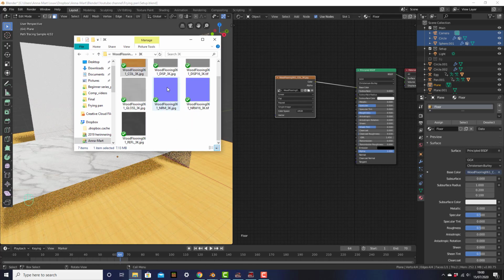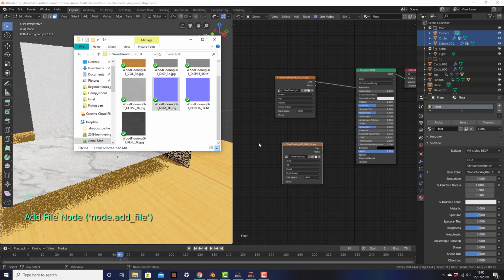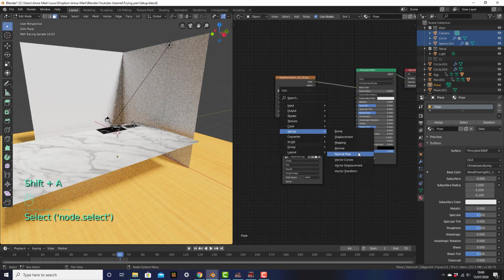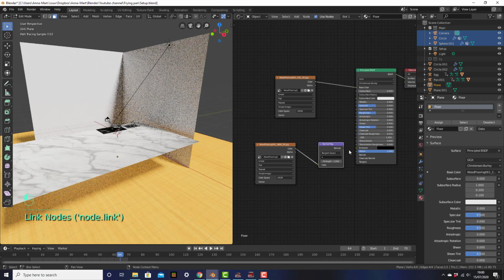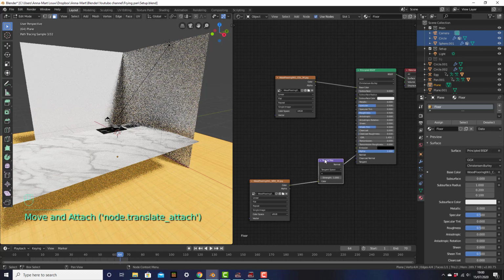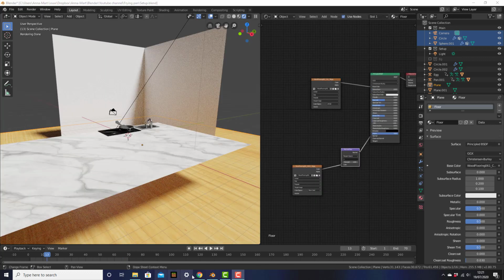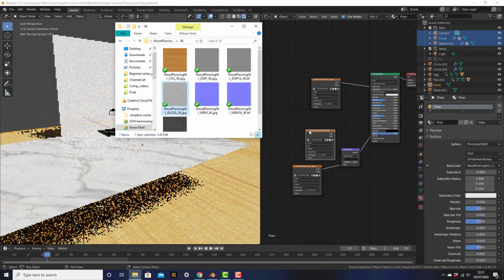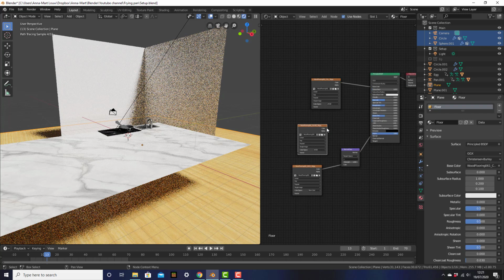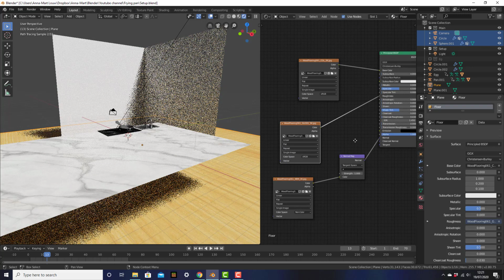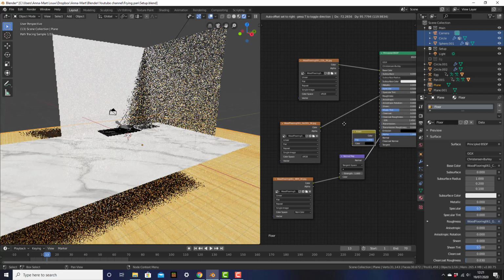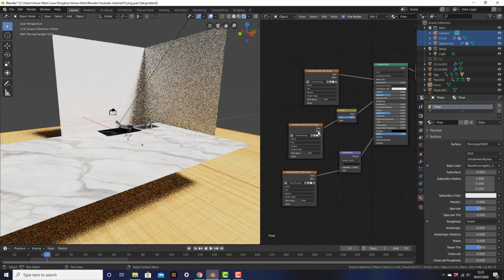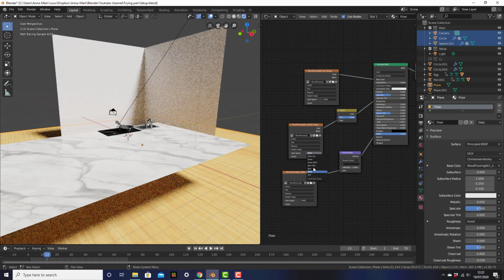Then we want to do the same thing with the normal map that we did previously. Add the normal node first. And then we also want to add the roughness. But once again, we only have a glossy map. So select glossy map, drag it inside, connect it to roughness. But then we also need to add the invert node. So Shift A, search invert, and drop it in between them. And then just remember to change the glossy and the normal map nodes to non-color.